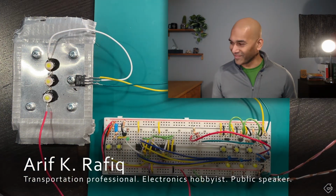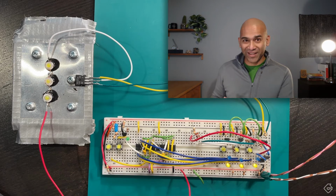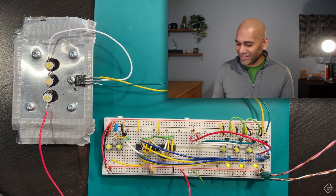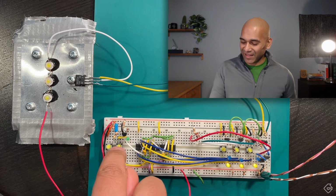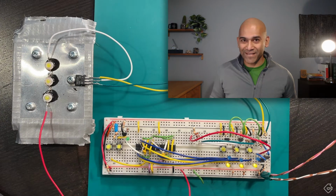This is nice. It's working really well. The hardware that we have right now, we've got our 3 LEDs run with 3 different current paths and a single switch that allows me to ramp up that intensity. All right, but as you might imagine, we want to make it better.